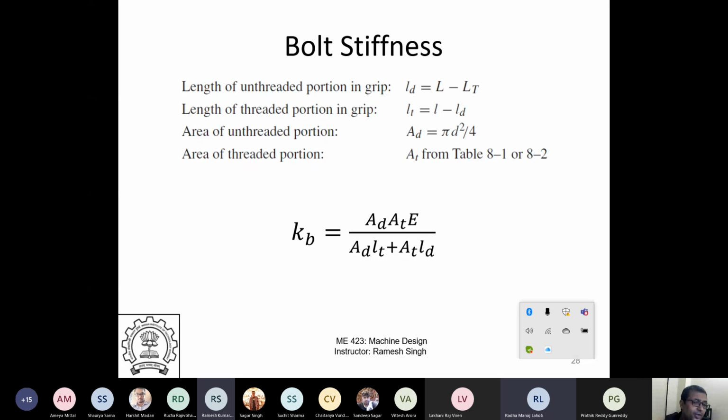It's a very good question. So basically, if you require very high torque, torque tightening, you may not want just a fixed head in the bolt. You would want to be able to tighten from both sides. So typically, the studs are used in flanges and other applications where you need torque tightening. If you require a very high level of tightening, you will use a stud. So you can have a finite amount of torque on this side and a finite amount of torque on the other side also. So you have tightening from both sides.